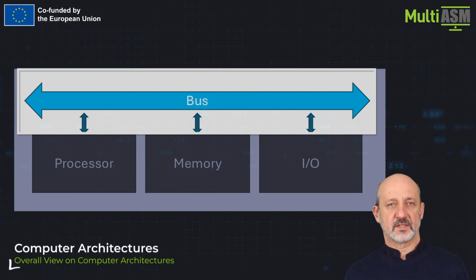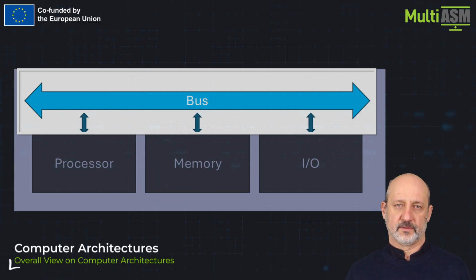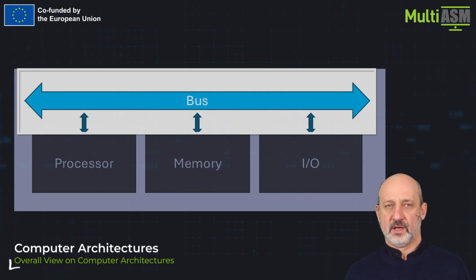The address bus is used to select the placement of data which the processor wants to transmit to or from memory or a peripheral. It also addresses the instruction that the processor fetches for execution. The address bus is one-directional. The address is generated by the processor and delivered to other units.